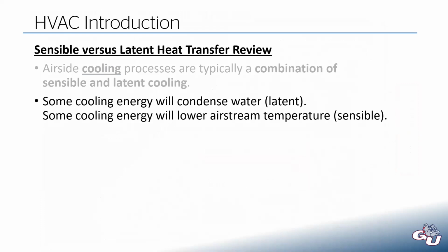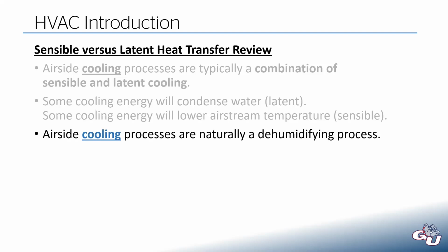So the energy that's used to condense the water, that's the latent component. And then the energy that lowers the temperature is our sensible component. Any airside cooling process, just by the nature of how they work, is naturally a dehumidifying process of that airstream. They are dehumidifying the air that's running through them.